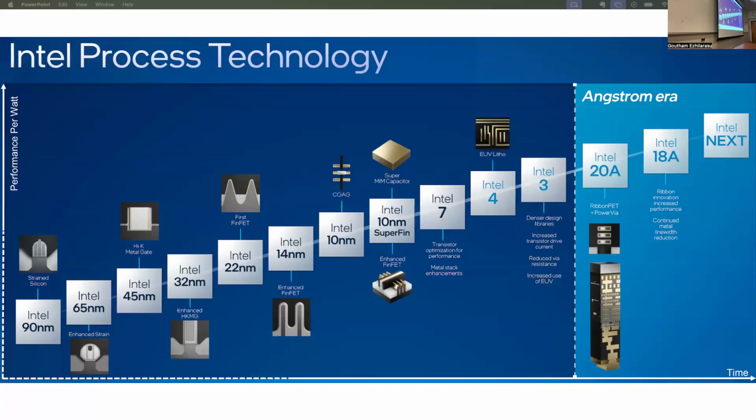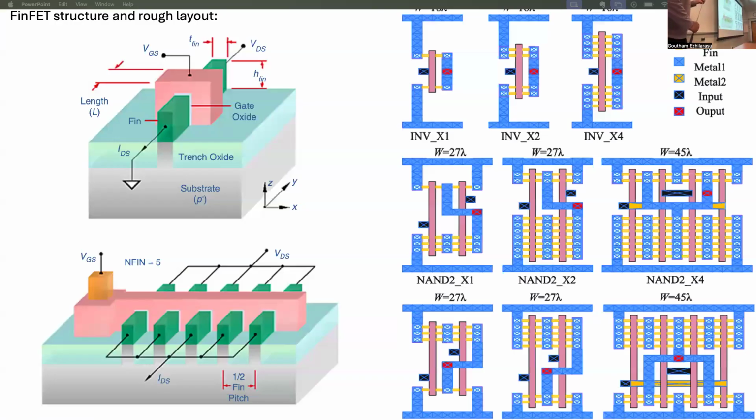So the sidewall spacer has two benefits, okay? And also, another benefit of the sidewall spacer, which is what is used in the FinFET, is that the sidewall spacer itself is used as a hard mask to make the fin. So it has many important benefits, right? So I hope you understood the structure of the FinFET.